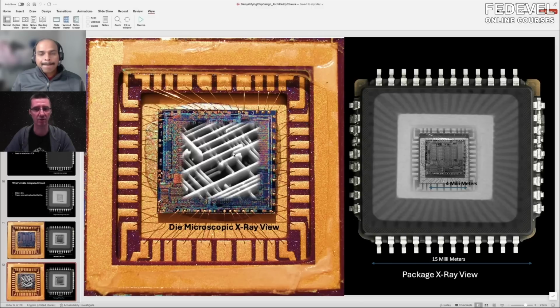So basically, when you design a chip and run simulations, you not only run simulations once for one situation, but even for the limiting values of not only one thing like temperature, but limiting values for several manufacturing process parameters, and for crosstalk.